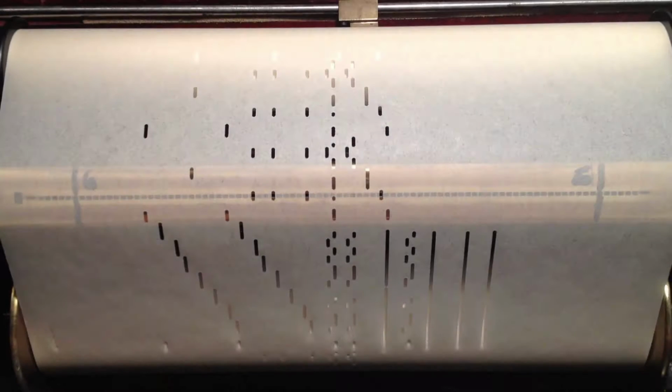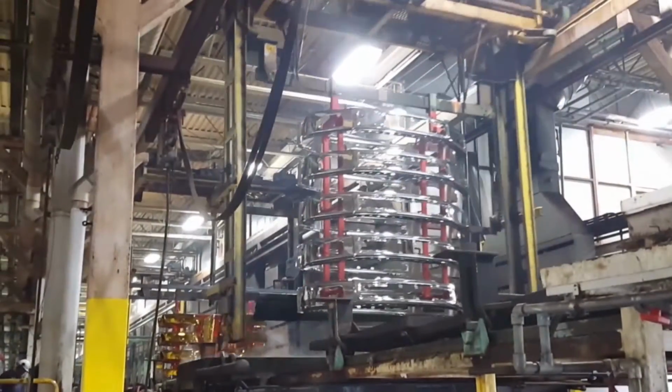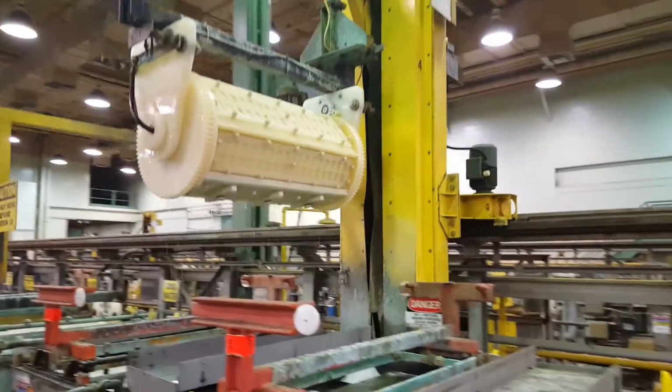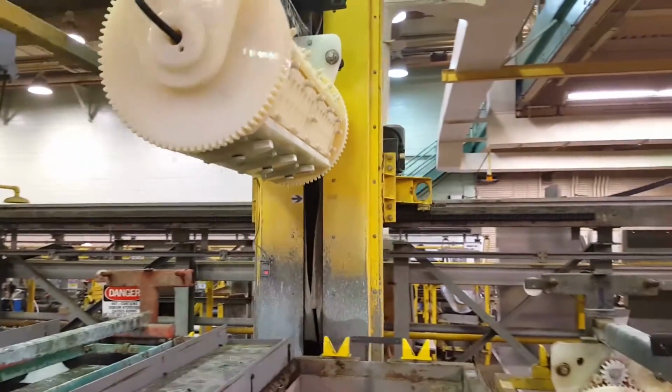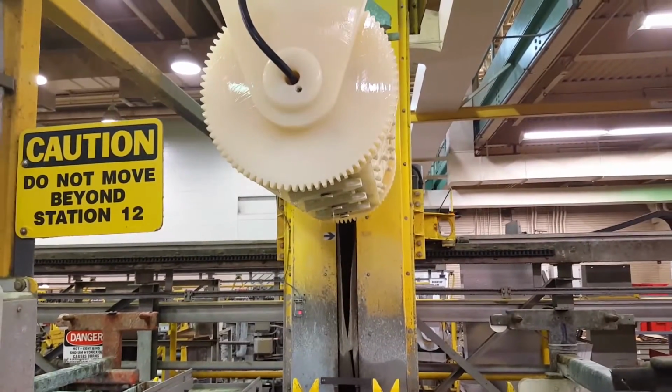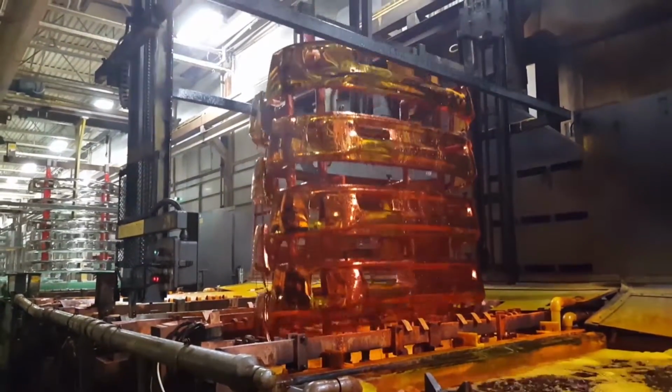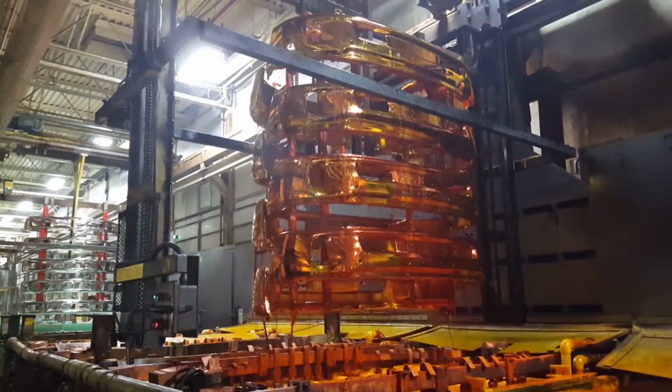Fixed timeway control is the traditional pre-planned scheme, similar to the notes in a player piano roll. Crane moves are planned well in advance and repeat in a cycle. Since the system operates in a coordinated fashion, any single problem in the line will cause the entire multi-crane system to come to a stop. While known for their highly optimized production capability, fixed timeways are unable to handle mixed recipes or frequent adjustments.